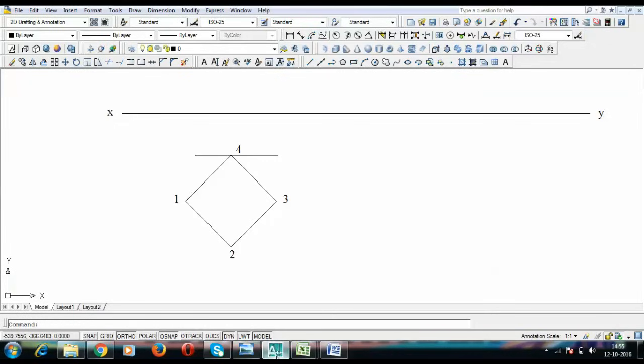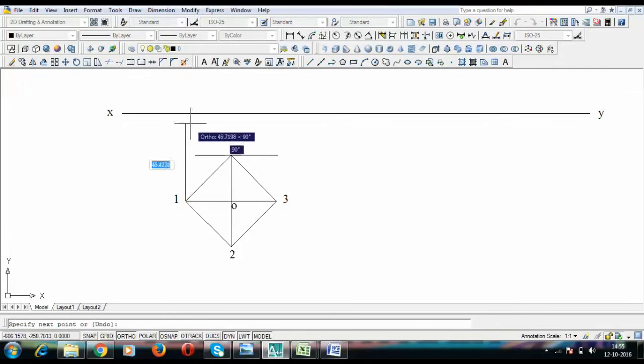So in order to find the apex, let us draw these two lines, and from 4 to 2. So this is exactly how a square pyramid would look like. And I'm going to write O over here. That's it. Fine. So this is the top view. We have begun with the top view, and then correspondingly we're going to make its front view. So let us start.